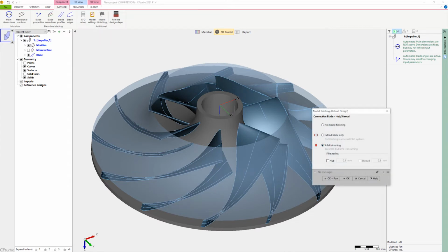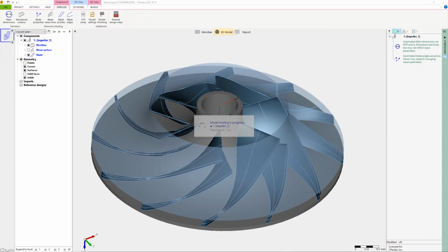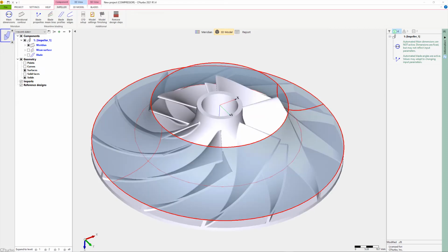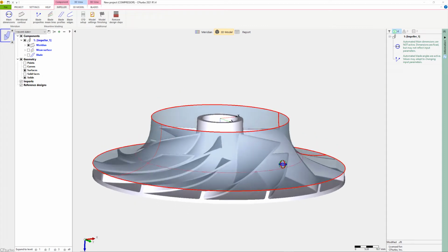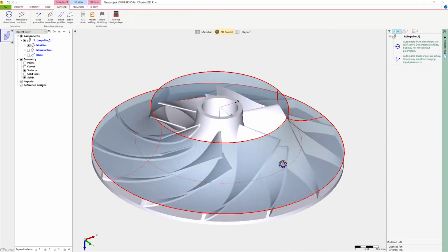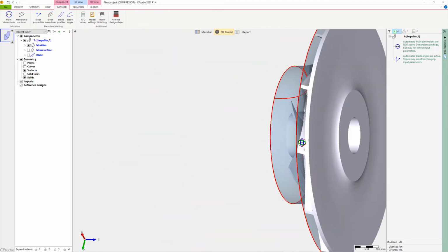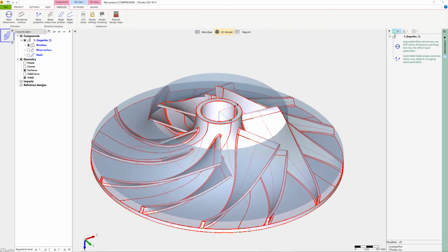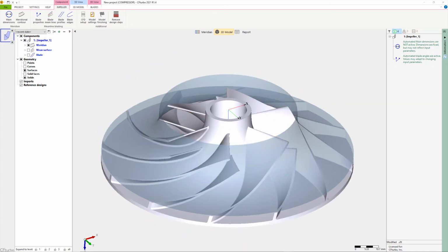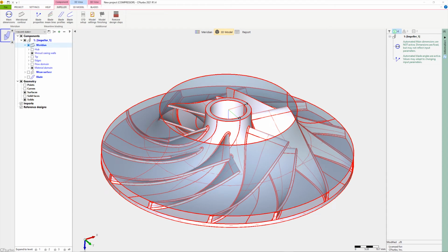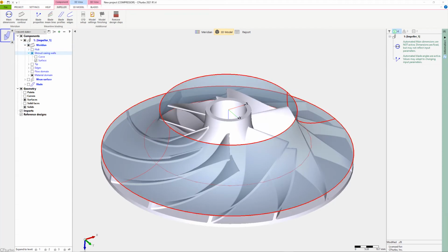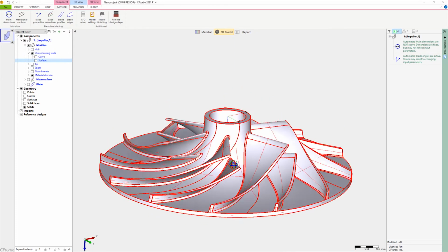On the right side of the window, the user has options to see blade-to-blade calculations or blade surface calculations as in the previous design step. The 3D view of the blade profile directly shows the model in three-dimensional CAD. On the right side of the window, the user can configure the same view options as in the previous design step: area, progression, Mach number, relative and absolute velocities, swirl, blade loading, etc. are available. The 3D modeling of the blade edges can be seen in real-time modifications.